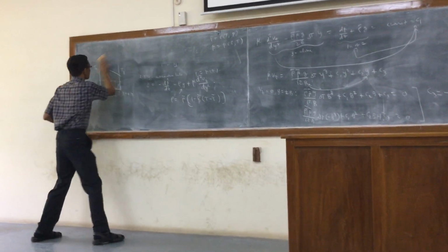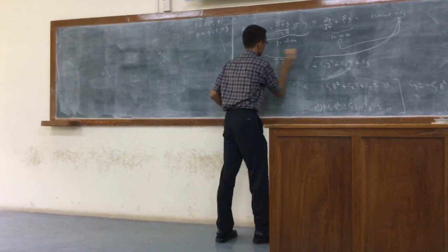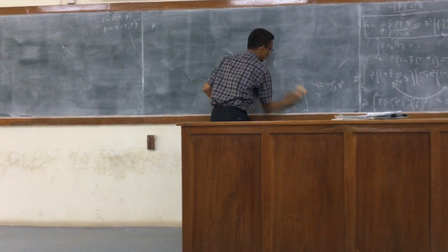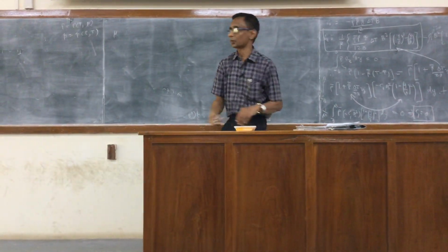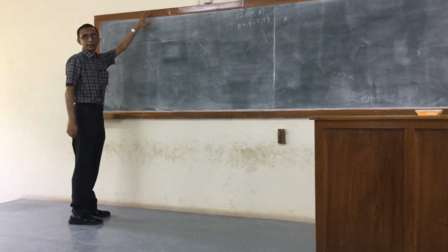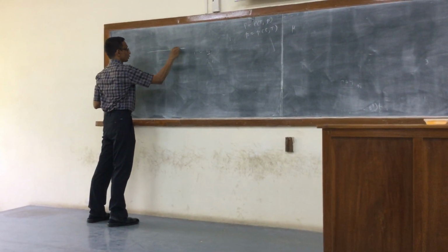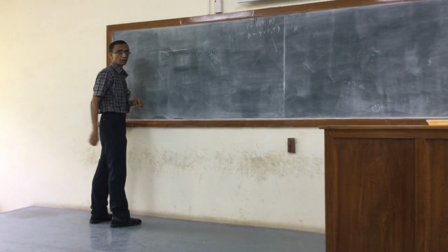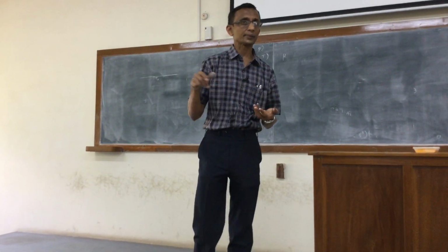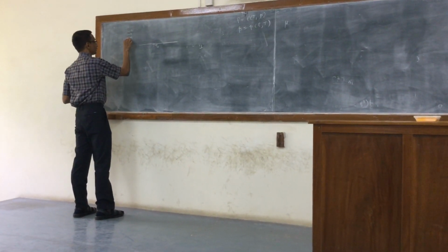Another instance where the Boussinesq approximation is used indirectly, we are not going to use it directly, is the consideration of the so-called thermal boundary layers. I'll briefly discuss that. We see the flow over a flat plate. Now on top of the flow effects, we also consider that the plate is maintained at a temperature T0. It might be at a higher temperature than the fluid, so the fluid is getting heated as it passes over the plate.